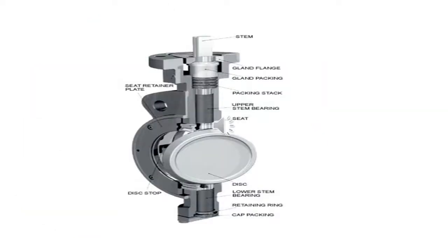The packing material of valves can be widely varied. It could be Teflon, O-rings, graphite cord, or some other material that when compressed seals between the shaft and the body of the valve, preventing leaks. As valves are used, the packing may start to leak. This leak can be stopped typically by just tightening the flange or the packing nut, which are generally located under the handle of the valve. When it is tightened, it compresses the packing material, thus stopping the leak. At some point in time, though, it may not work anymore because the packing is fully compressed. And at that point, the material inside the packing gland will need to be replaced.